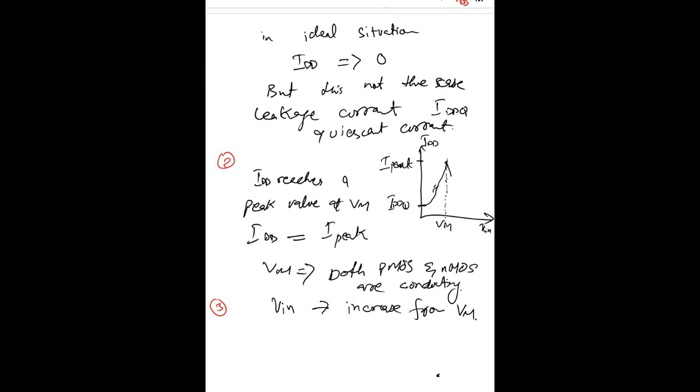So we have a discharging current, but there is no current from VDD to ground, so our current starts decreasing. It decreases to a value equal to IDDQ. So again we have the same voltage at the output.